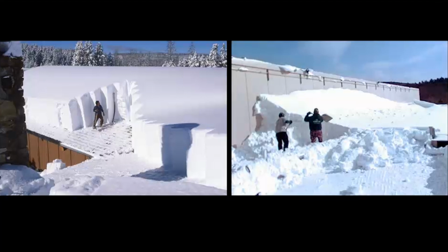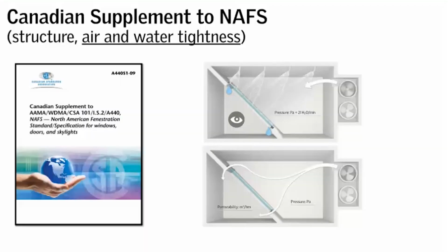Now the image on the right is a little bit different. This is two roofs. This is a snow drift that's developed due to the second wall construction leading up to the higher roof. We had a project north of Montreal where we were looking at a skylight that was going to run right into that upper wall. And we had to play around with the design a little bit because they did anticipate drifting like you see in this image.